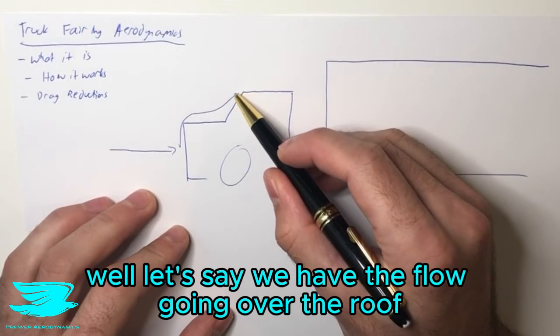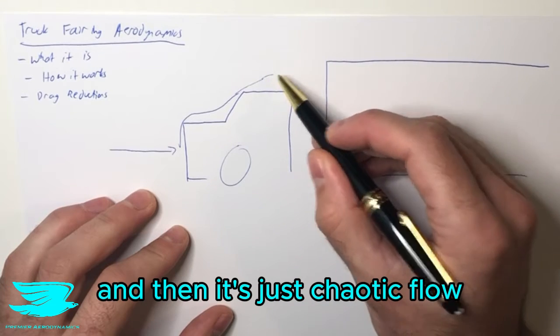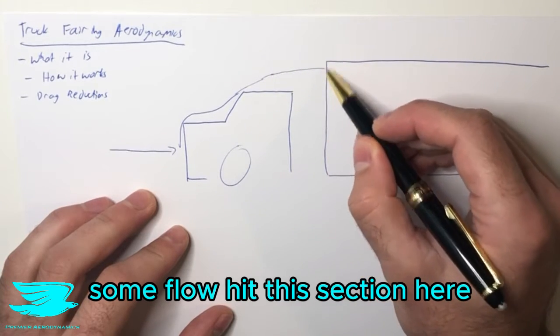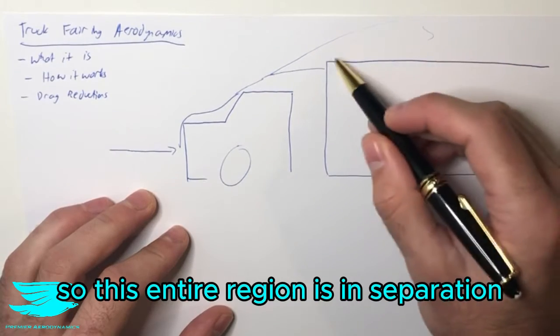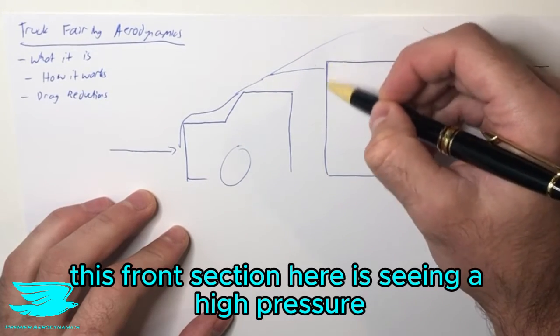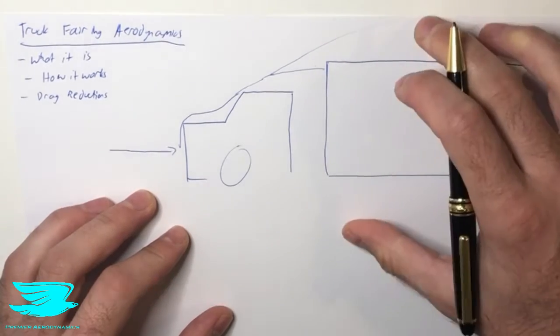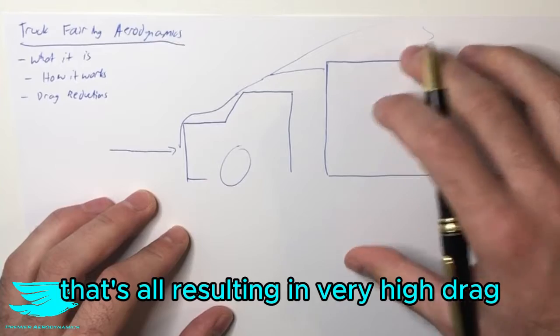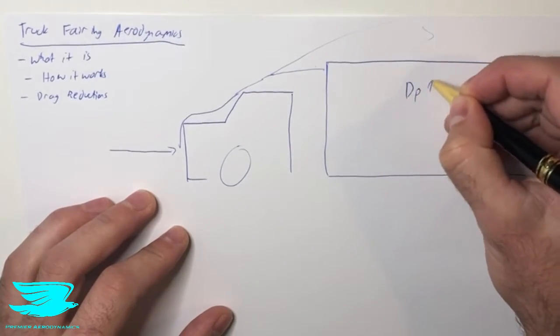Well, let's say we have the flow going over the roof and then it separates. And then it's just chaotic flow. Some flow will hit this section here. Some flow will come up and just continually separate. So this entire region is in separation. This front section here is seeing a high pressure here and low pressure at the back. That's all resulting in very high drag, predominantly through pressure drag. So DP skyrockets a lot.